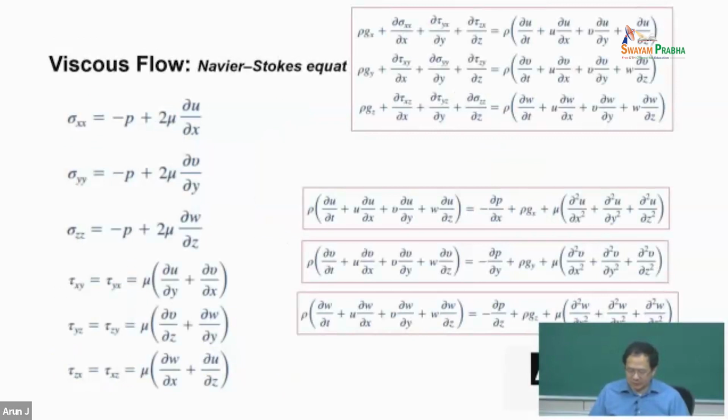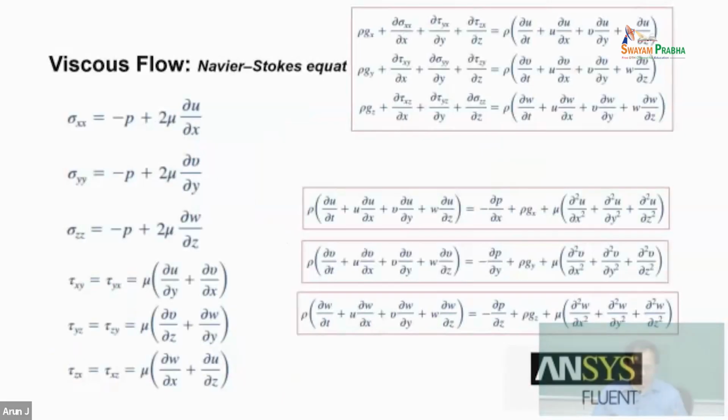You don't need to remember all these equations. I just try to let you know that below is the equation for viscous flow, and for potential flow we don't consider viscosity or compression of the flow. The more general case is the Navier-Stokes equation, and you can use ANSYS Fluent to solve the Navier-Stokes equation, which addresses the viscosity problem and also considers vortices or other non-ideal losses.